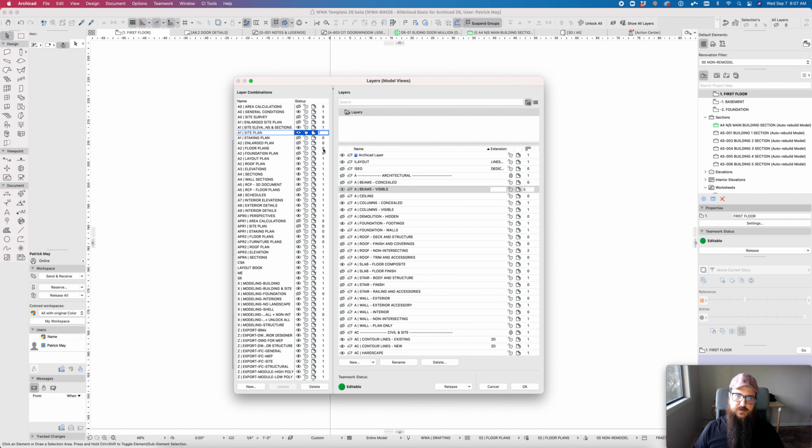One thing that's critical though is that when those layers are visible, they should be intersection group 1. So what this means is that anything that's on this group is going to interact with other things on that group. We have 3 primary intersection groups that we use. 0 is used for a layer that's not visible, that we do not want to interact with any other layer, even other layers that have a group 0. 0 will not interact, will not intersect.